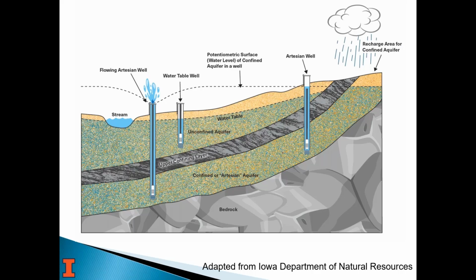You can see the well on the right is artesian because the water level comes up higher than the aquifer, but it's not flowing. But then down lower on the landscape, because the landscape's so low there, that well is actually flowing. And that dent in the dashed line for the well is because if I had a well at every single location where there's a dash, that's what the water level would be.